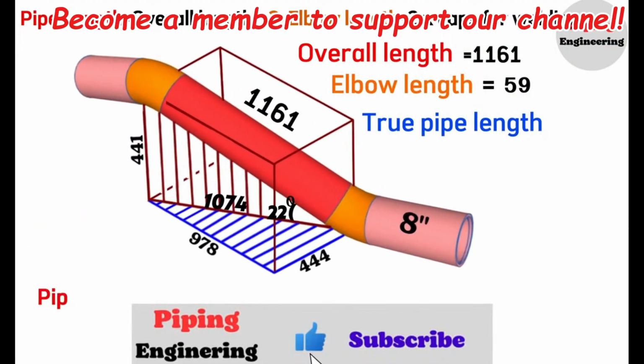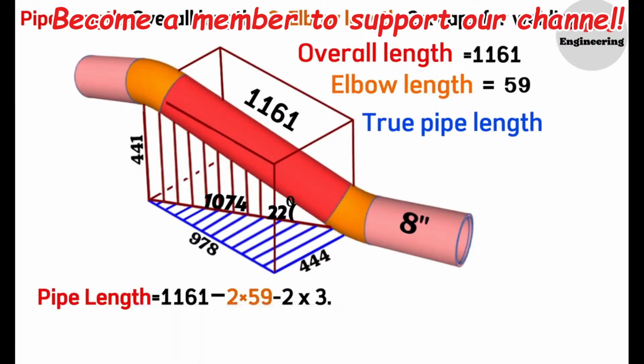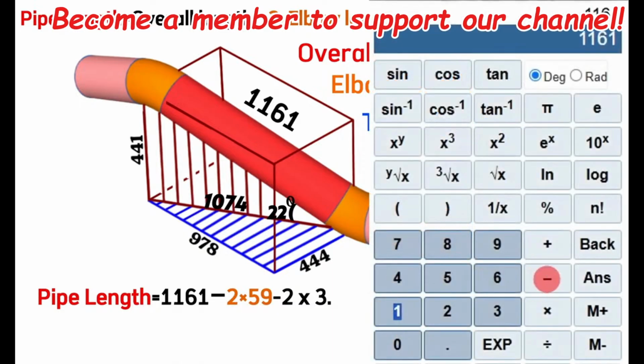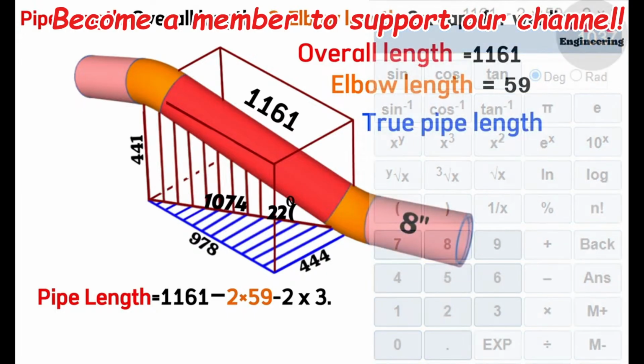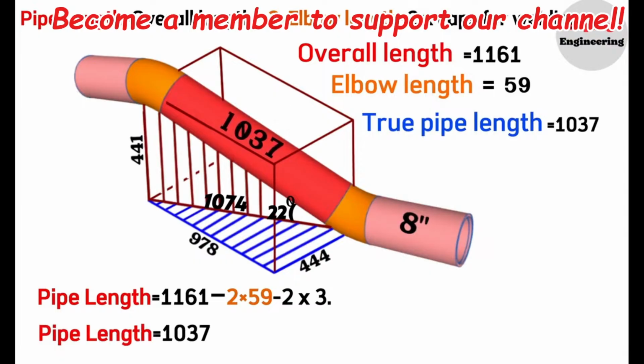Pipe length equals the overall length 1161 minus 2 times the elbow length 59 and minus 2 times 3 for the caps for welding. Using a calculator, 1161 minus 2 multiplied by 59 minus 2 multiplied by 3 equals 1037. So, we calculated and found that the red-colored pipe length between the two elbows is 1037 millimeters.